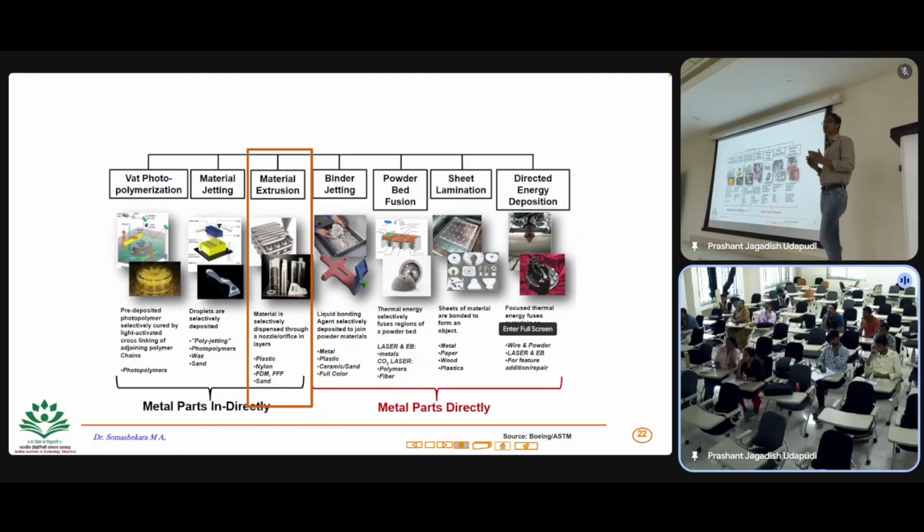And then you can have a series of products that you can manufacture, because you're trying to print one material and then see the product coming out of it, right? With a single material, or maybe you can combine different powders, but you'll be able to get the component, which is more of making the product with maybe a single material or a combined composition. But when you want to vary the composition gradually, or form different alloys within the structure, that may be a little difficult when it comes to powder bed fusion.